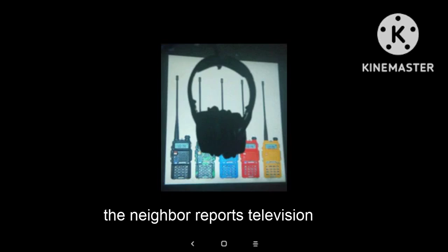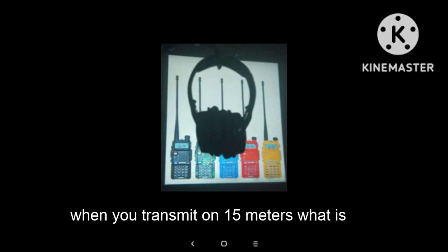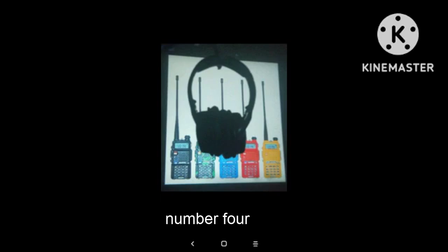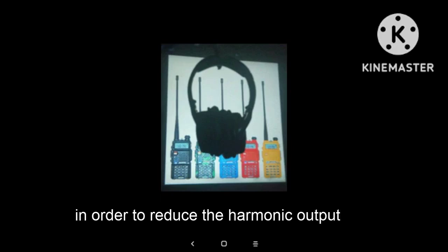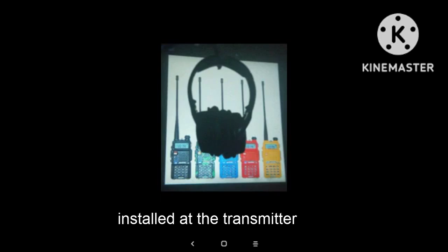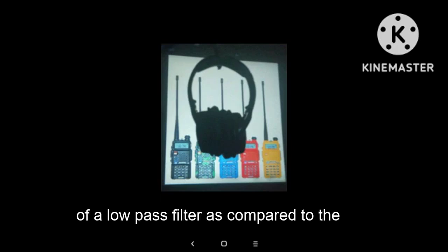Number 3. If a neighbor reports television interference on 1 or 2 channels only when you transmit on 15 meters, what is probably the cause of the interference? Harmonic radiation from your transmitter. Number 4. A bandpass filter will only allow certain frequencies through. Number 5. In order to reduce the harmonic output of a high-frequency or HF transmitter, which of the following filters should be installed at the transmitter? Low pass.